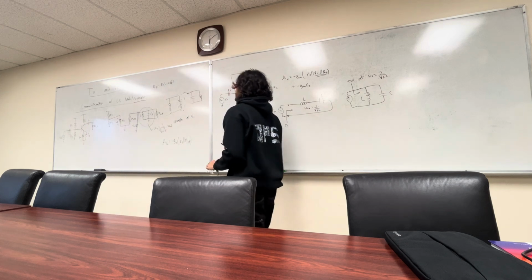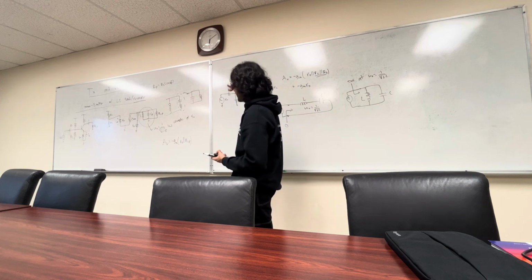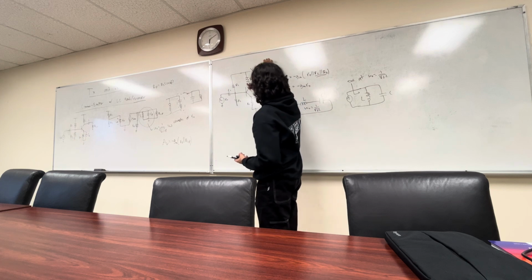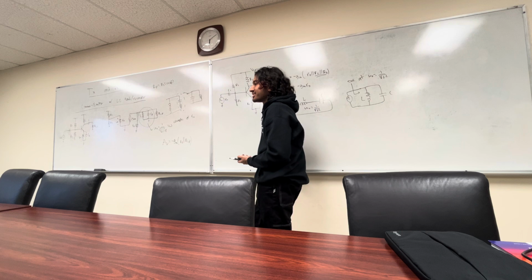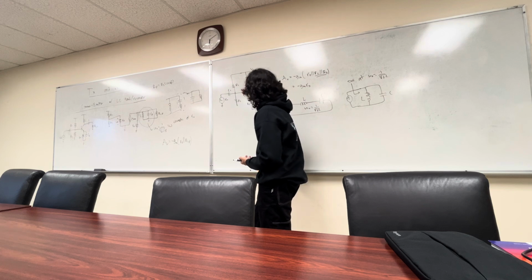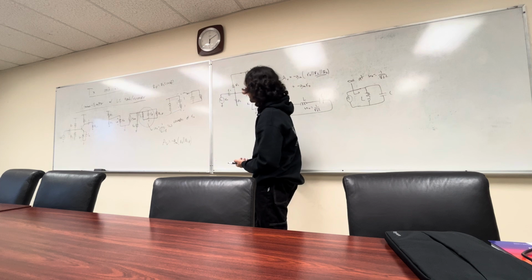Now, let's talk about a few things here. You may say, well, we still have R naught in parallel with something, so why couldn't we just make RC infinity? Anyone tell me why? Can't just make RC super large? Yeah, R naught's always going to cause it to decrease. But in terms of biasing, right? If you draw any type of current, you're going to immediately drop all the voltage across it, per se.